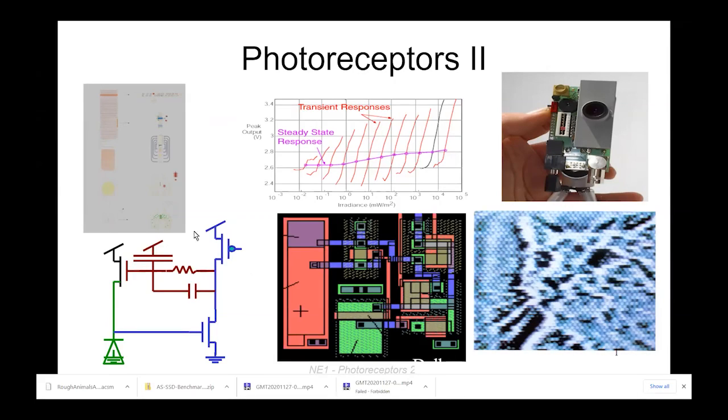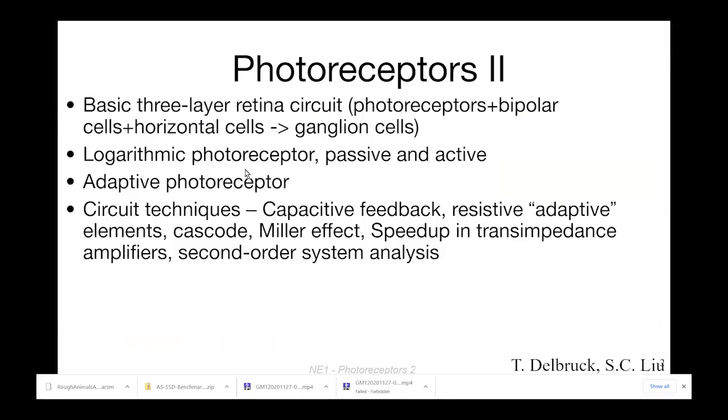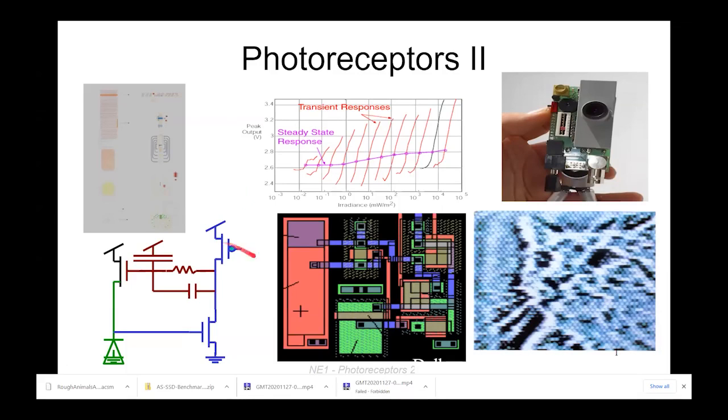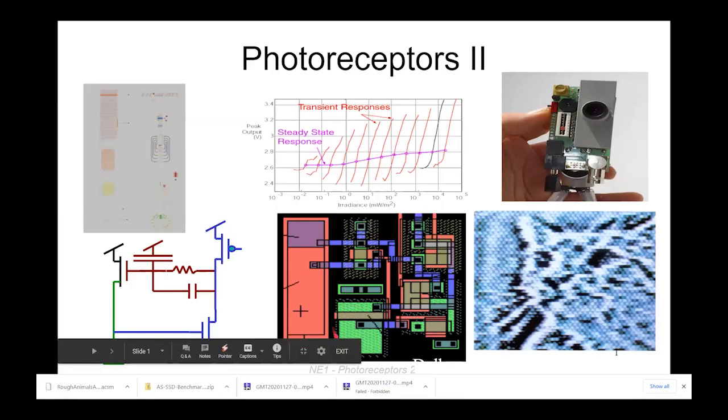And if you actually lay out a circuit like this, it's quite cool because it sort of looks like what you expect, right? Here is the photodiode. In this particular case, we made the photodiode just by extending the source of this NFET. So it's just the N source drain region. This is looking down on the thing. Here's this transistor. Do you see where that transistor is? It's this one right here. That's the photodiode down there.